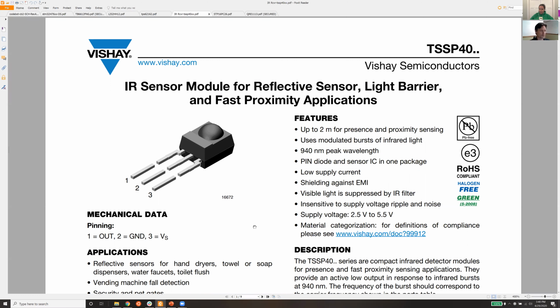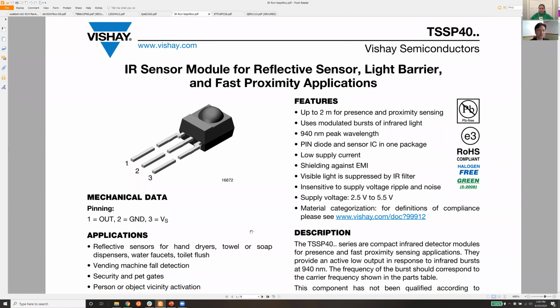We use the 56 for a reason, because we wanted to do something a little bit special with this. Vishay put out an app note a couple of years ago about using these things for distance sensing, and you can do that by modulating the frequency. So we don't always just use them at 56. They're most sensitive at 56 kilohertz modulation of your IR emitter, but if you sweep it down, you can gain some additional levels of granularity in your distance measurement. It's really interesting. You can look in BotCore to find a little bit more about that.